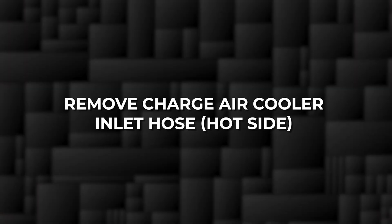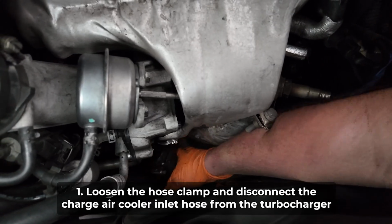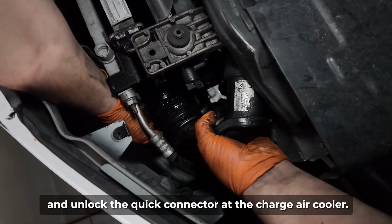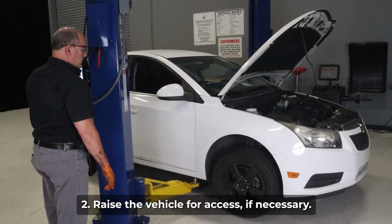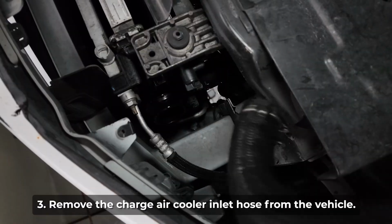We are going to remove the charge air cooler inlet hose. Loosen the hose clamp and disconnect the charge air cooler inlet hose from the turbocharger and unlock the quick connector at the charge air cooler. Raise the vehicle for access if necessary. Remove the charge air cooler inlet hose from the vehicle.